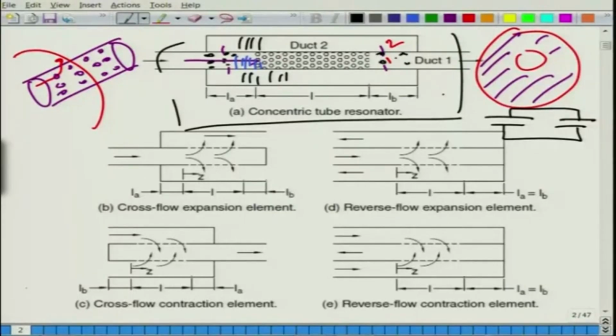Especially when it has a high porosity as we are discussing, that would basically act like your expansion chamber, a concentric expansion chamber, but it would still be 1000 times better than just leaving it like this because of flow separation. Even if it is fully highly porous, but fully perforated, it would do its job, at least it will provide you some attenuation, it will not be counterproductive. So, that is one thing, we should be able to analyze such things.